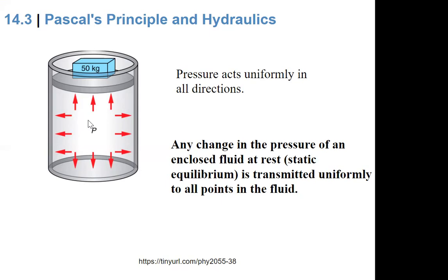Once this is changed, the rest changes accordingly. If this increases by, say, 500 Pascal, then the pressure on this wall will be increased by 500, and at the bottom it should also change by 500. So any change in the pressure in any direction will affect the other directions as well. That's Pascal's principle.